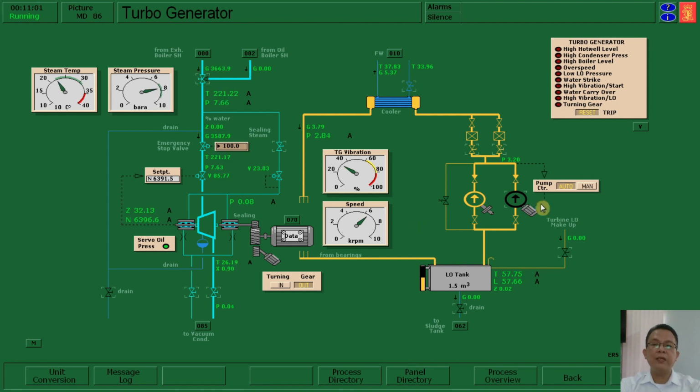So what's keeping? It looks like okay. So we need to counter check everything. So watch keeping follows. What to do next? We have to check the inlet pressure as well as the inlet temperature. Check also the outlet steam temperature, the shaft speed, the RPM. We have the trip indication, sealing steam pressure, vibration index, LO pressure inlet bearings, the lube oil tank level, tank temperature, and everything.